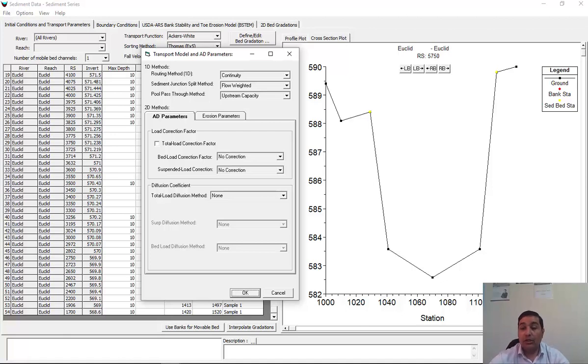This approach includes no physical limitations on sediment velocity, and depending on cross-section spacing and time step, often moves sediment faster than water velocity. Therefore, HEC-RAS includes an option that limits sediment velocity to the water velocity, only releasing sediment from each control volume that the water passing through the control volume can carry.